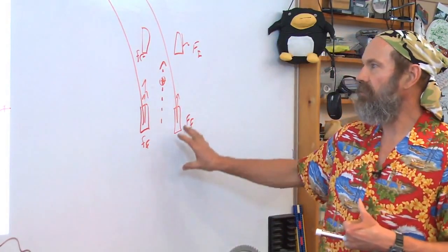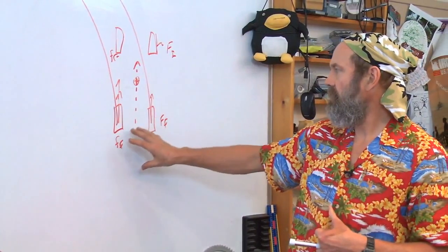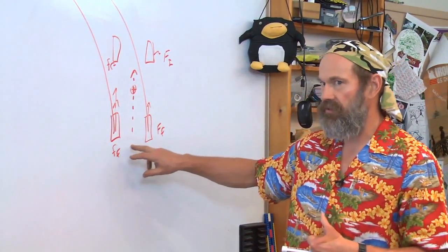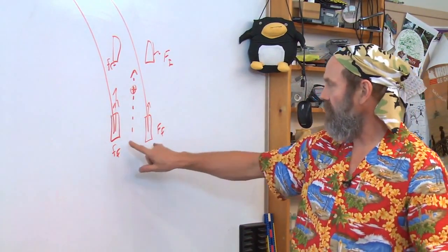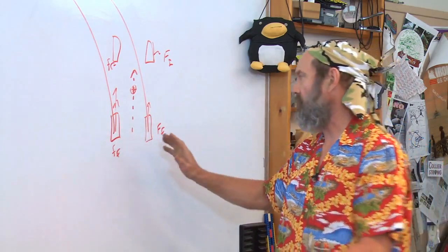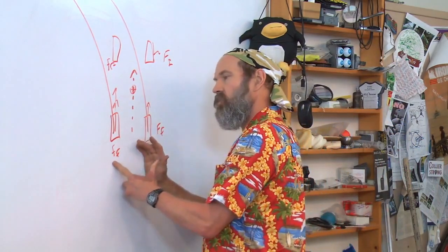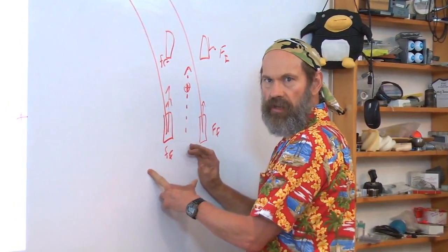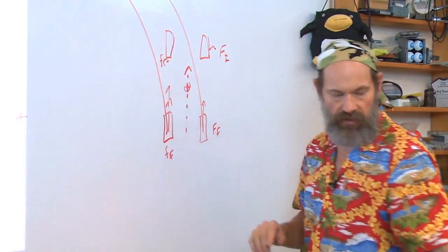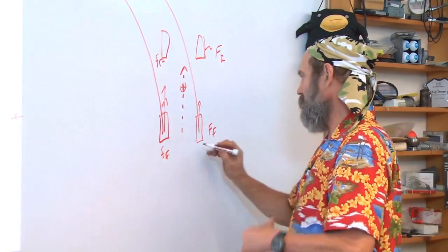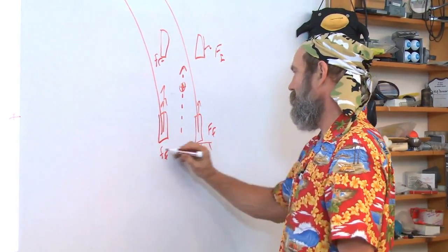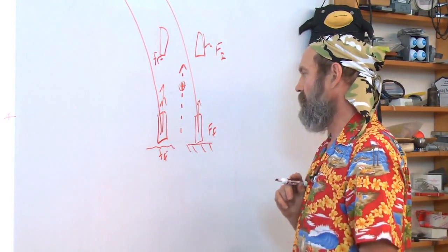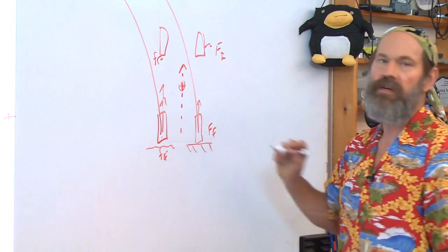Okay? Similarly, you can have a clutch built into your differential because a normal, what's called an open differential, will always send the power to the wheel that's the easiest to turn, and the other one will just sit there. So if this wheel here was on pavement, and this wheel here was on ice, this wheel would spin and that wheel wouldn't do anything.